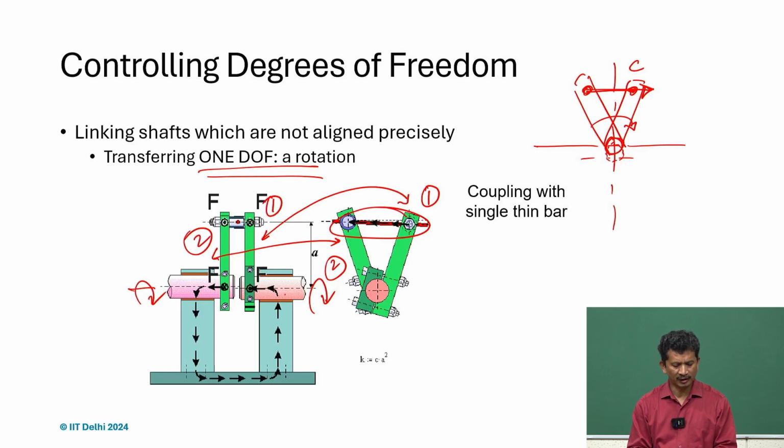But what we realize is that it is sufficient, and if there is any eccentricity or offset because of misalignment, or even of the axis, at the point of location where we put the arms, since it is an articulated link, it can move and shift a little bit and accommodate that. Even though the position is varying, it can change. So, the articulated link is good enough.